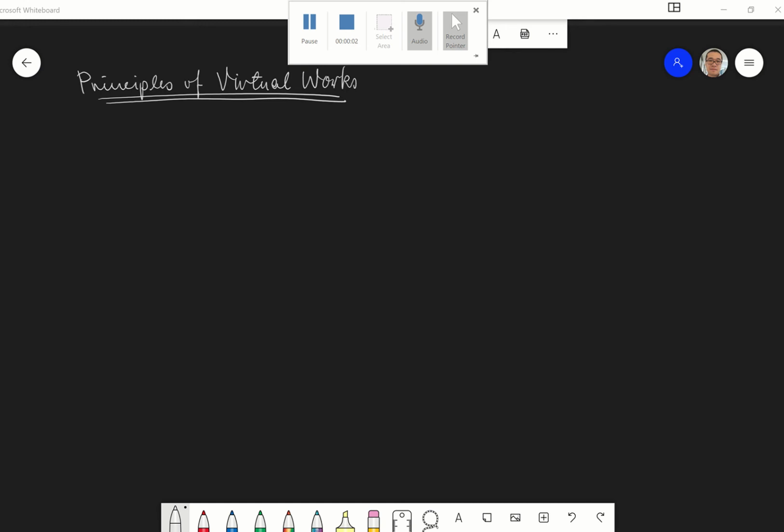So in the last few lectures, we looked at how to work out the stiffness matrix for some simple elements like the truss elements, for example. Now, the way we work it out is quite unique to elements with those types of shapes. But generally, if we want to work out the stiffness matrix for an element of arbitrary shape, and most typically, for example, we use square and triangle elements where the element is continuously distributed with mass inside each element.